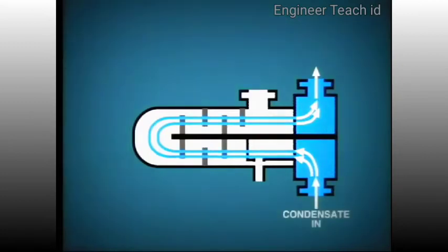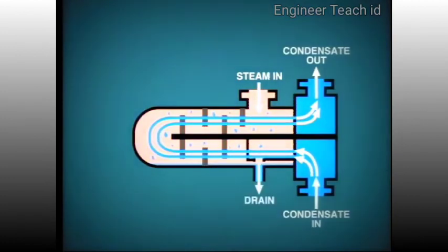This type of heater is known as a tube and shell heater. Water enters at one side of the water box and passes through U-shaped tubes to exit at the other side of the water box. The condensate is pushed through the large number of tubes, typically about 300, by the pressure on the condensate pump discharge. The tubes are supported and held in place by internal baffles. Extraction steam enters the shell and fills the space around the tubes, consequently giving up heat to the water passing through the tubes. The steam condenses and falls to the bottom of the heater from where it is drained, passing through the heater drain system back to the condenser.